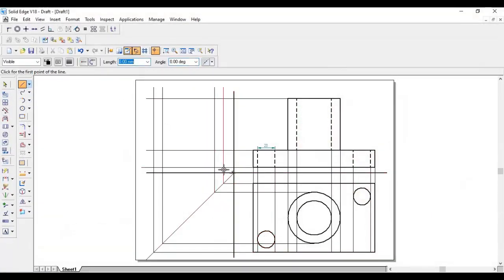So here I will cover this block with total dimension from this point to this cross exactly 80. You can enter 80 also. Then the height is 20. Then close this one and close this one.